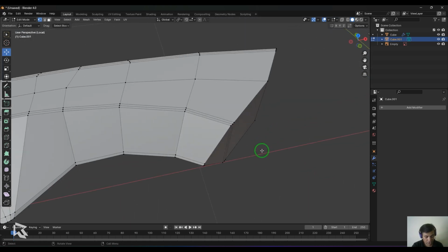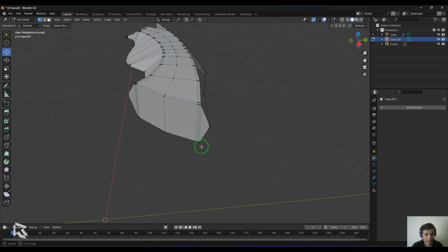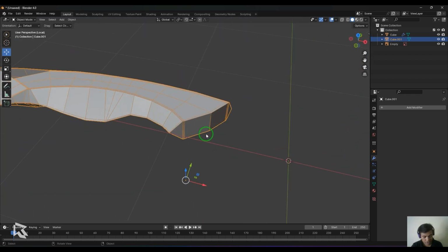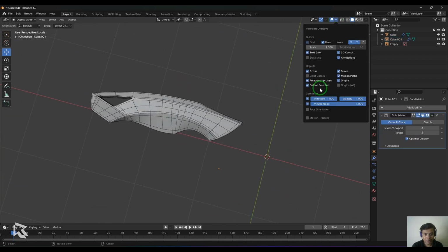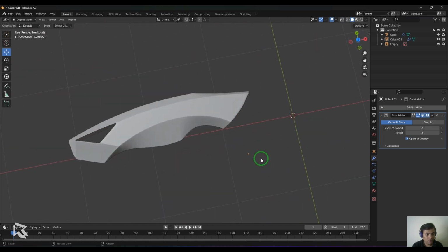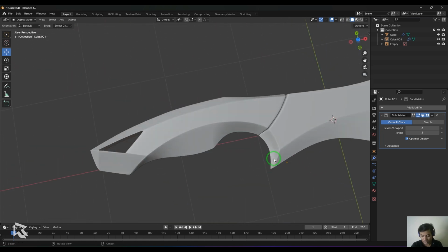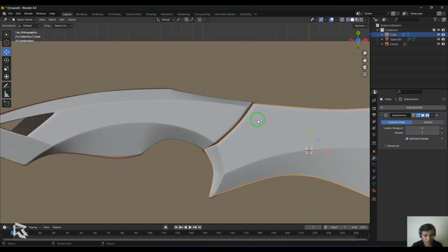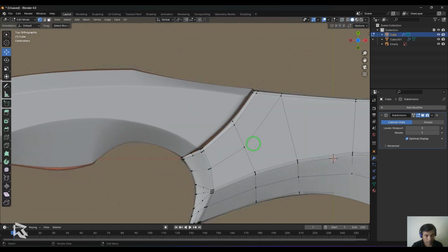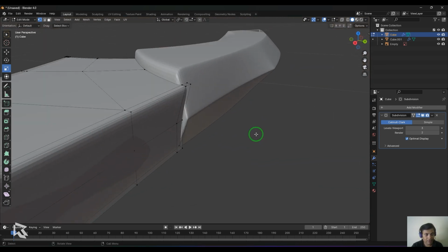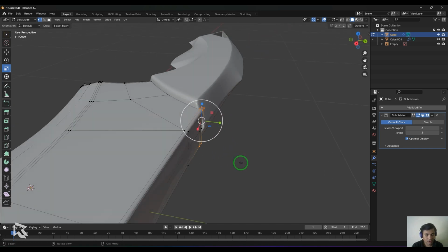Now once that is done, I press Ctrl R to add the loop at this particular point, and you get this. Now press Ctrl 3 just to have a look at the handle, how it actually looks in terms of shading. Then bring back your forward slash and see how you're going to match this one. So the points have to be penetrated here into the blade. Now I can use the scale tool, slightly scaling in both the axes there. That has to be penetrated.